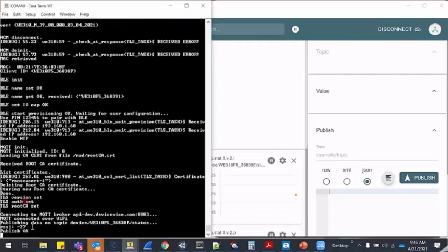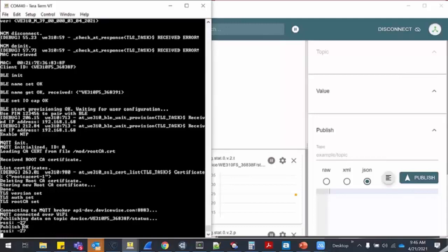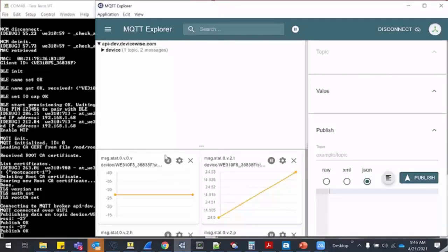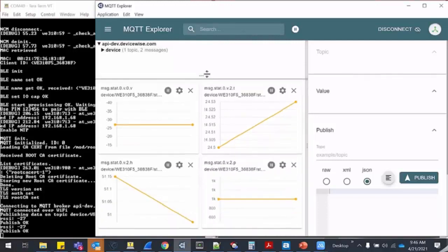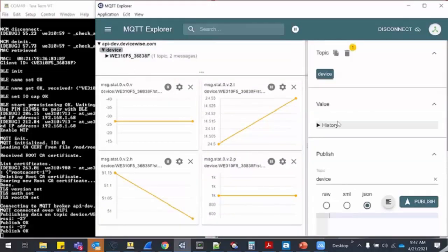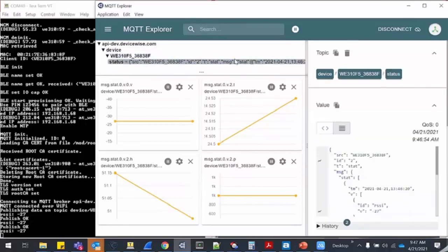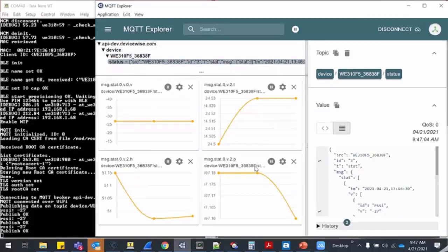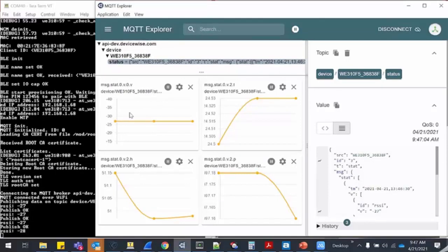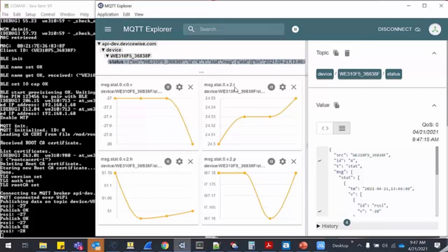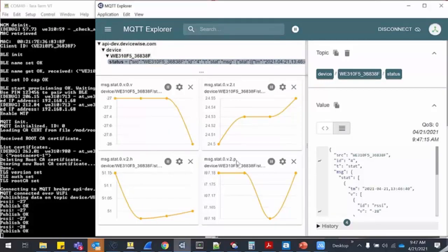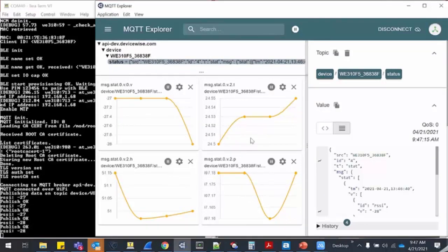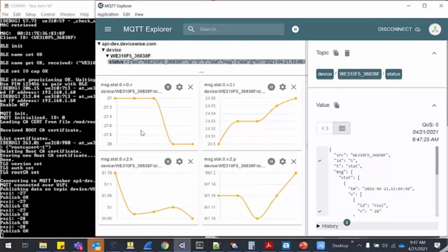You can see as my system starts publishing this data, it is publishing the signal strength. So I have captured some of these parameters. Basically, it's a JSON string we are passing continuously, and we try to plot the data using this tool, where V indicates the signal strength part, and T is temperature, and H is humidity, and P is the pressure. So we are taking all this pressure sensor information from the Bravo board, and giving it to the Wi-Fi module and trying to plot that graph.